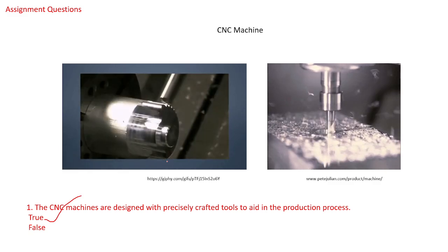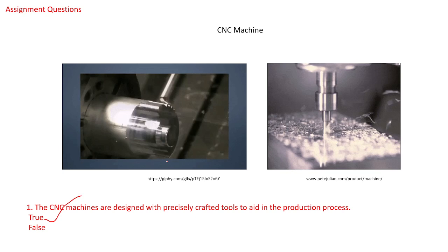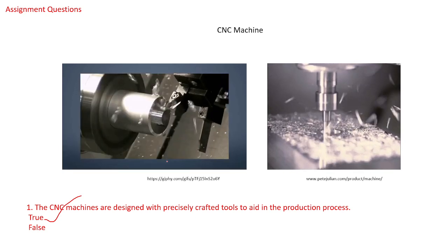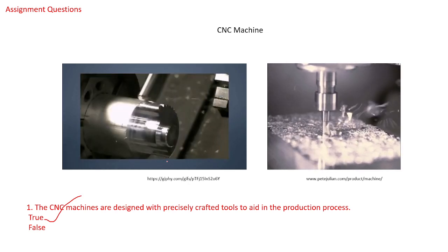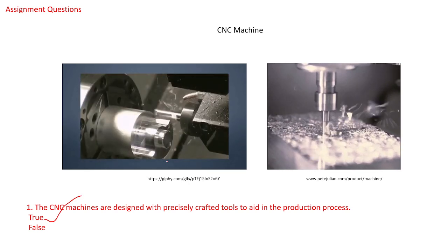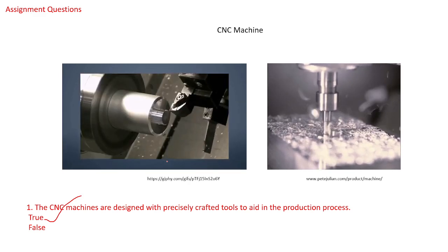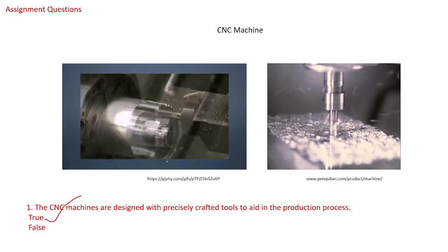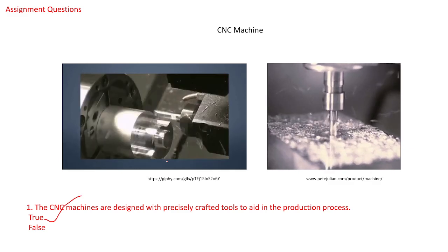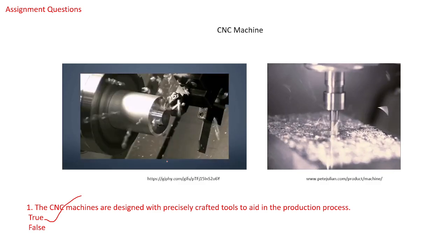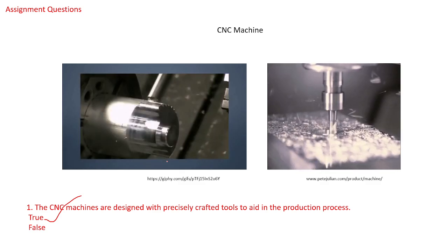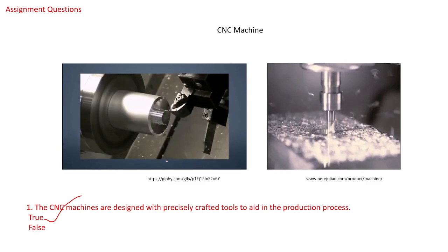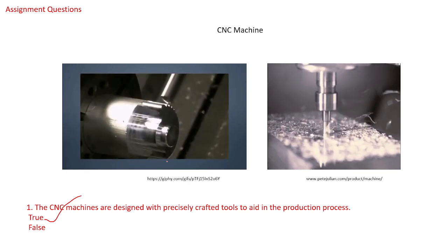Basically, lathes are typically two-axis machines that have just one spindle, but the turning centers can have up to five axes, and are more versatile in terms of cutting ability. Also, lathes do not have a protective enclosure around the machine, and do not have the high production capabilities of turning centers. So those are the basic differences between CNC lathe and CNC turning center. But both of the machines work on the same principle, right?